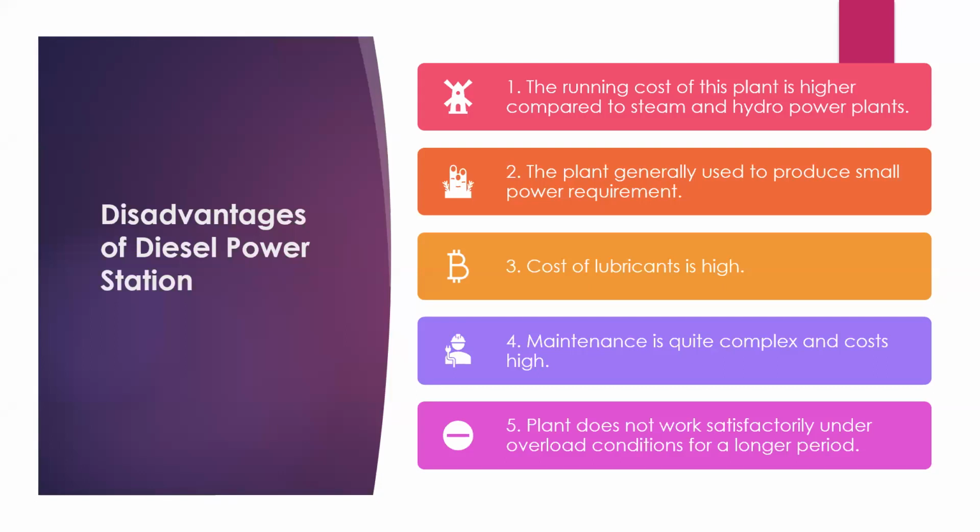Maintenance is quite a concern, and the maintenance is quite complex and cost is high. The maintenance means the lubricating oil has to change, and the air intake duct filter has to be removed, and whatever pollutants or dust are there, that should be removed. Because the maintenance work will keep on coming. That is one of the concerns of your diesel power plant.